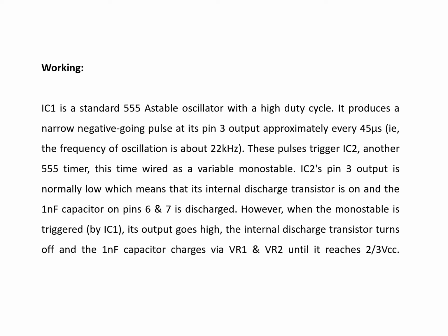Without soft start, a high starting current will occur from the supply side. So the filament gets stressed. Filament means our halogen lamp filament, I am telling. So frequent lamp failure will happen due to this high starting current and stress of the filament. This will result in reduced life of the lamp.